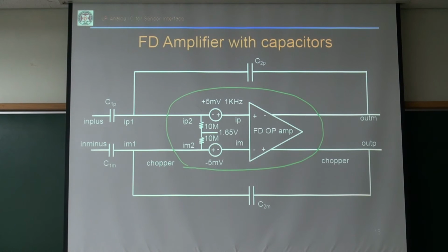All right. Let's go to the more realistic one. So this part is for DC biasing. Say I have this 1 pF and this 0.1 pF, so my voltage gain with the feedback is 10. This differential output voltage is 10 times this differential input voltage.